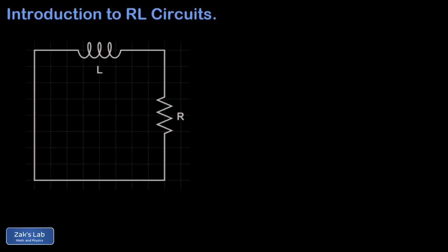Our next major goal is to determine the current as a function of time if we turn the power source off. So this time our initial state is the steady state in which I is equal to V over R. We then remove the power source, but current is still allowed to flow. In other words, we shorted out the power source. So in our picture of the circuit, the power source is simply gone. Current is allowed to continue flowing clockwise for some amount of time until it winds down to 0.